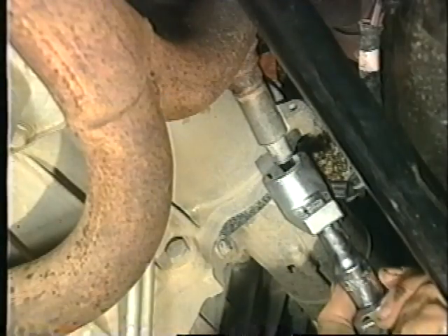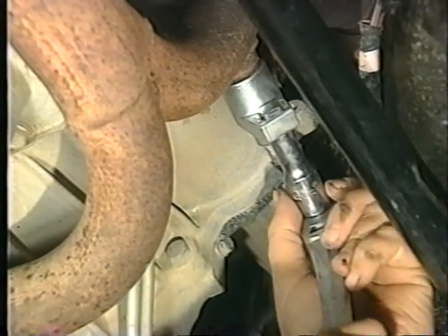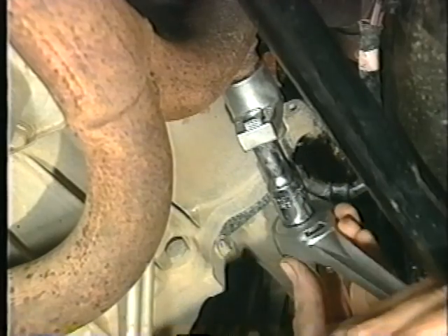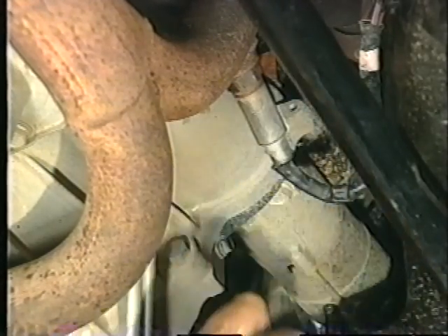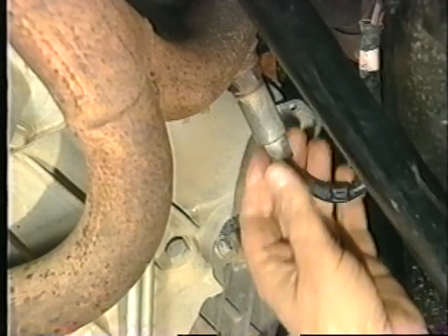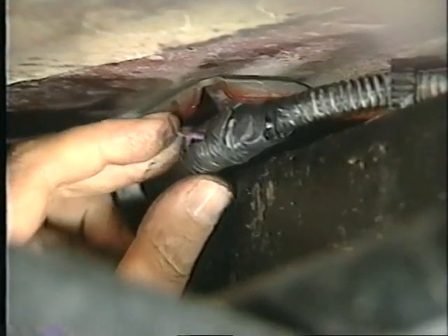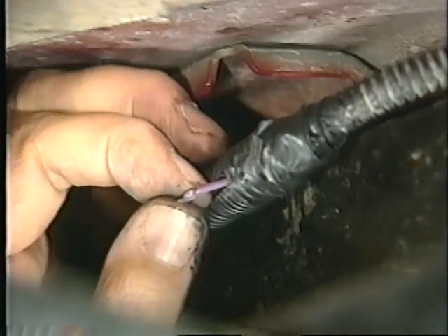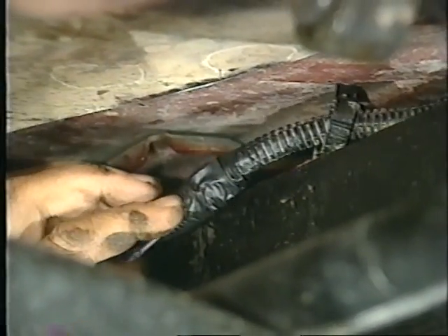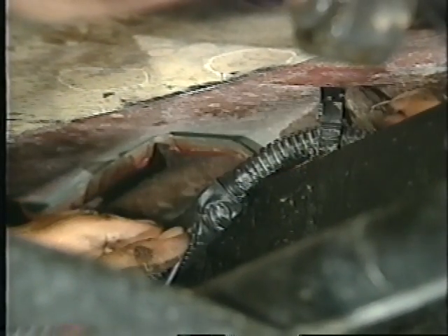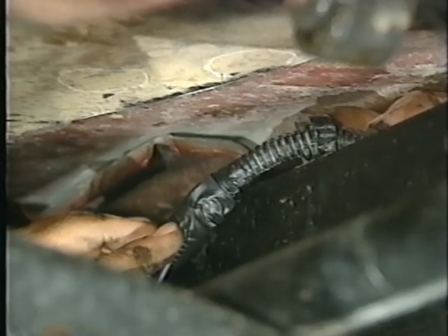The only thing you can do at this point is replace the O2 sensor. But don't stop there, because the problem is only half solved. You have to locate and eliminate the leak, or the condition will quickly return. The engineers told us that they've seen wiring that's been damaged by chafing against metal parts, or even melted from contact with the exhaust. This kind of damage is usually caused by missing or improperly installed harness clips.